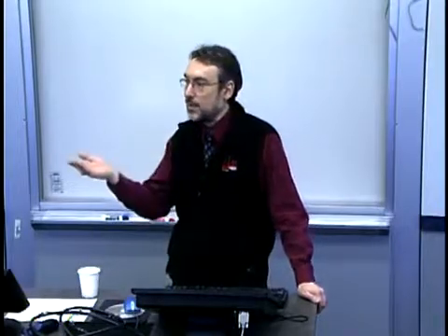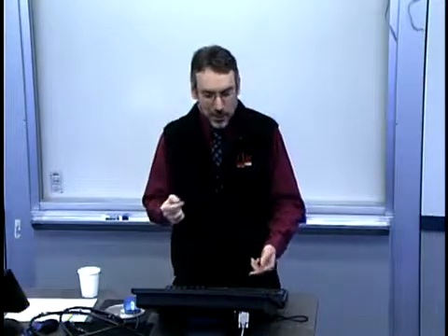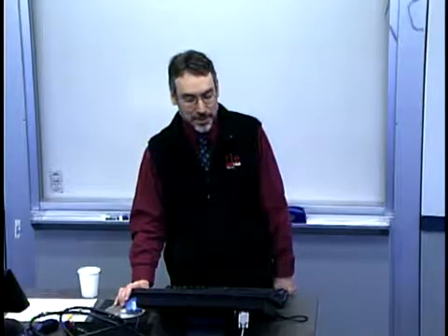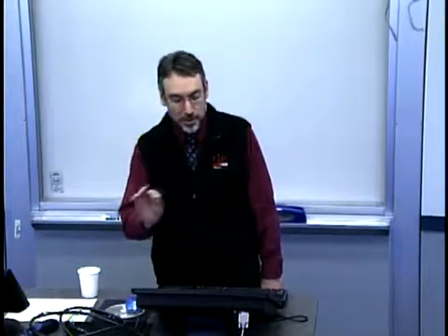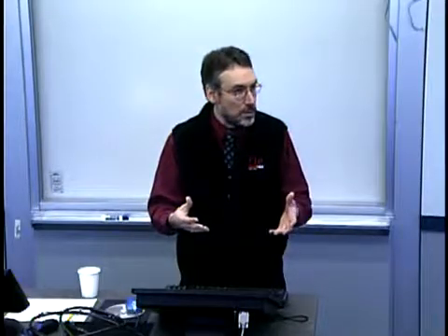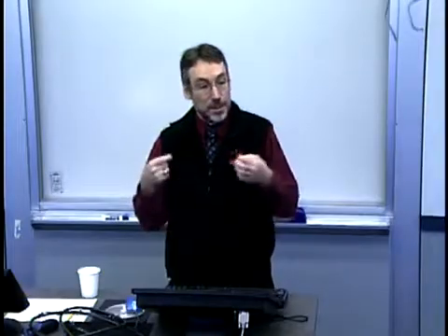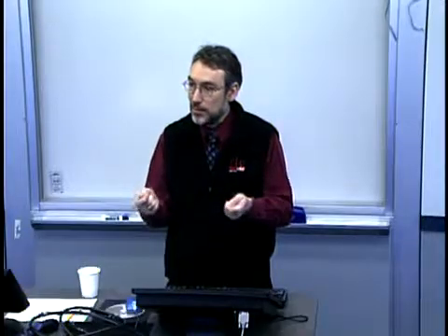So one might even apply some statistical methods to ask: is there a statistically significant mean difference between this set and this set of data? So it may look like a long-term trend, or it may simply be a reflection that there is a setup change on the equipment when a new shift comes in, or there may be just inherent differences in how the operator interacts with the equipment, right? How they load the part might be slightly different.